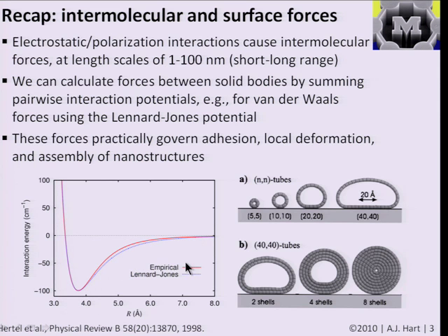In practice, we saw some examples, and we'll see many more throughout the semester, of how van der Waals forces practically govern adhesion, local deformation, and assembly. A lot of things govern assembly of nanostructures, but one thing that gives attraction, and can be screened or enhanced, is the van der Waals forces that can lead to assembly of things into bundles and lattices and so on.